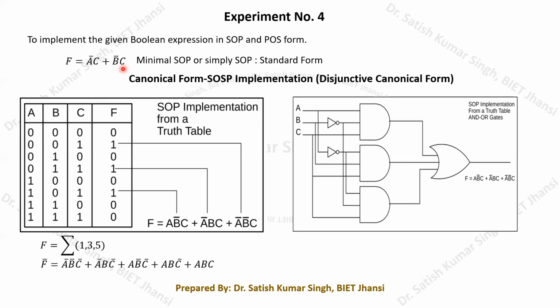Remember that we are seeing multiplication here, but generally it is a dot, like a dot c or a bar dot c. This dot or multiplication means an AND operation. Similarly, this plus signifies the OR operation. It is not a general sum like in mathematics, but rather a logical OR operation. This way we can construct our truth table. Based on the combinations of your a, b, c, sometimes the function becomes 0 and sometimes it becomes 1.